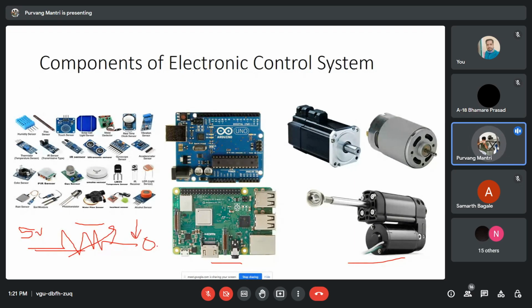So the microcontroller will come to know that if there is no output, it means the temperature outside is cold. But if the temperature sensor is placed in warmer conditions, the resistance is going to be least, almost near zero. So 5 volts will just flow through, and the output value would be 5 volts. The microcontroller will know that as the output value is 5 volts, it is hot. Okay, so this is the basic understanding of sensors.